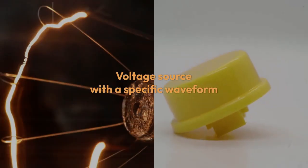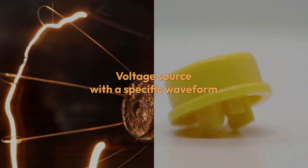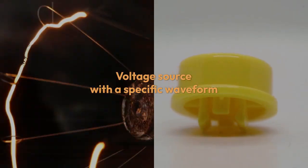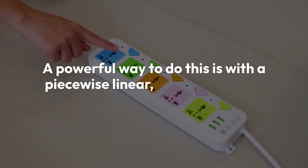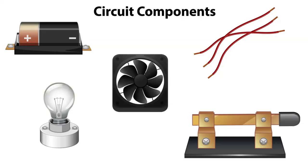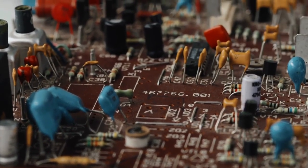Next, to model the bounce, we won't use a simple ideal switch. Instead, we can use a voltage source with a specific waveform to drive our input or represent the button's output directly. A powerful way to do this is with a piecewise linear, or PWL, voltage source. We will define a series of points that illustrate the bouncing. We'll start with the button in its unpressed, high state.